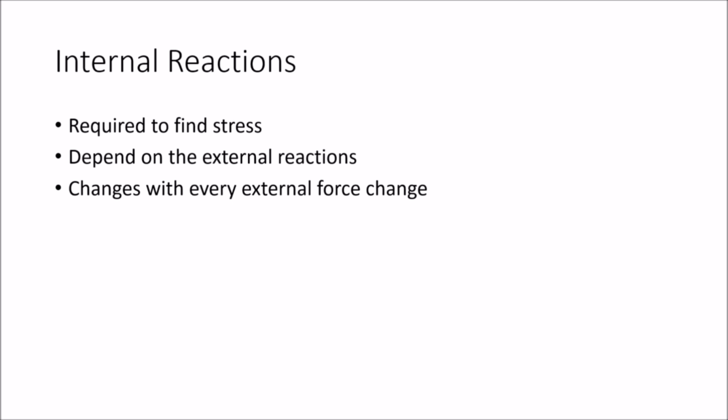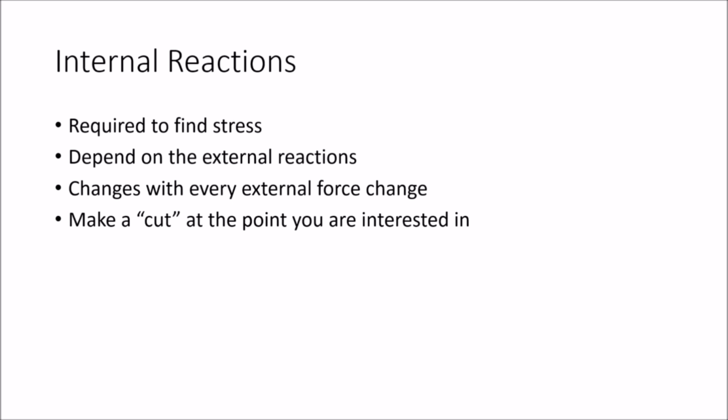When we want to find the internal reaction at a specific point, you should make a cut at the point you are interested in. That way, you can find what the internal reaction must be in order for that cut piece to be in static equilibrium. We won't worry about dynamic or accelerating forces in this class. Everything will be static. This idea of making cuts is similar to what you will have done in statics when finding forces in trusses.